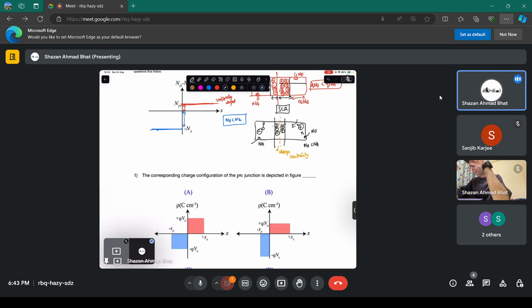In order to find the equivalent number of positive charges, the negative charges will need more positive charges on the N side to balance their particular field. Let's say if this had been equally doped, then an equal number of charges would occur at the space charge region. The depletion width is going to be the same on both sides.